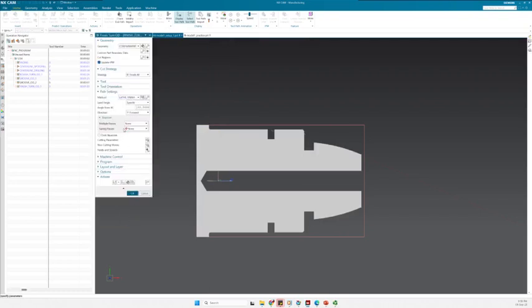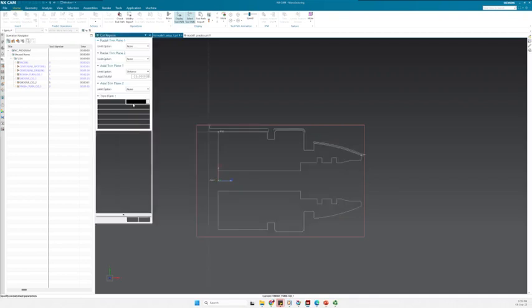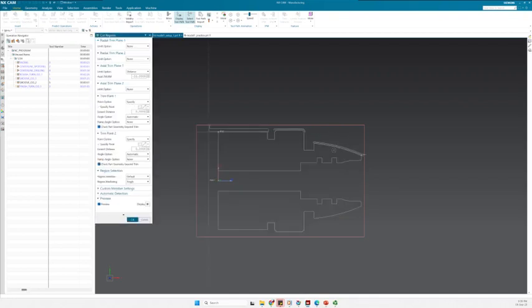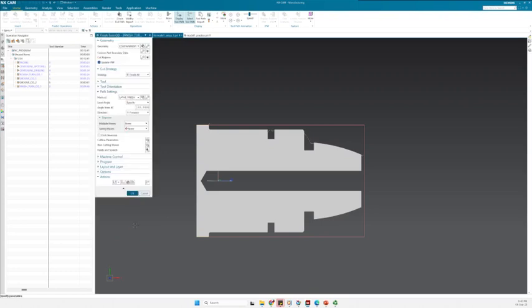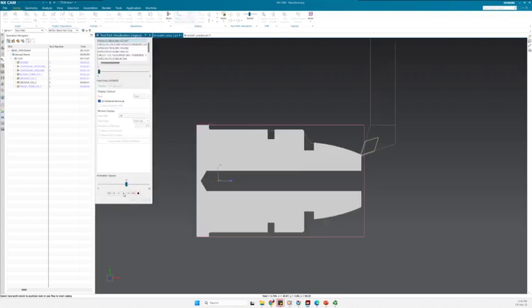So this is okay. And then I still needed to define that there are different multiple regions. So currently now 1, 2, 3, it understands 3, but by default the machining region is 1. So I search for multiple, I choose multiple, and then single direction. So I think now we are good to go. After that, well, let's try to see what will happen here.